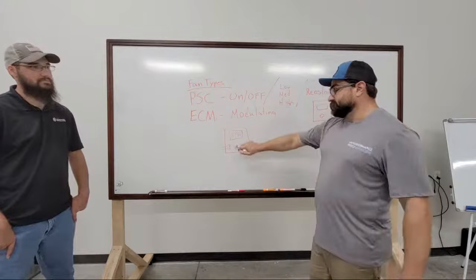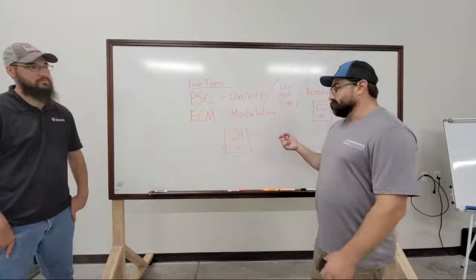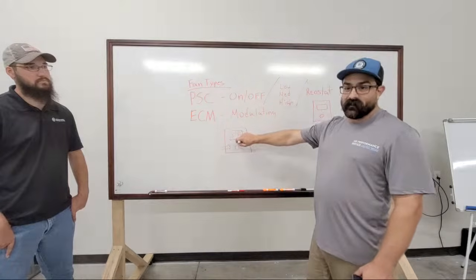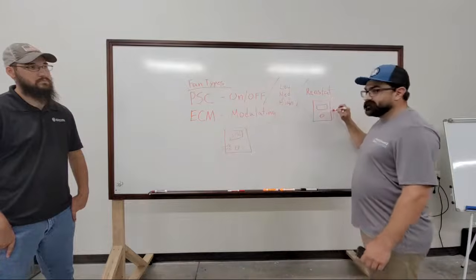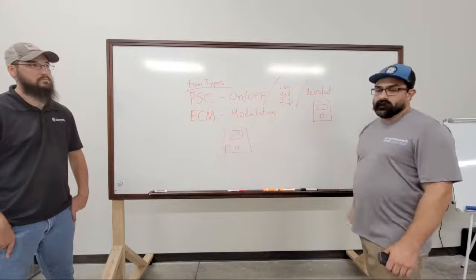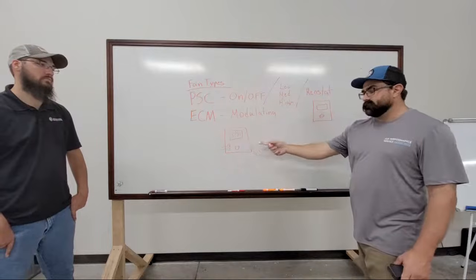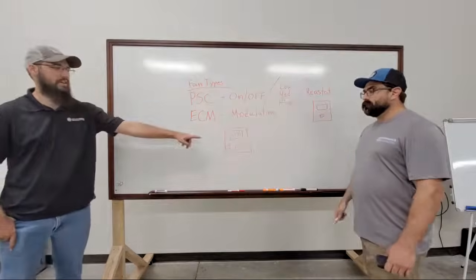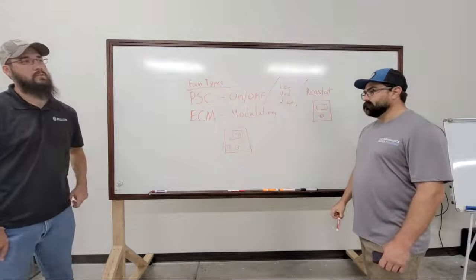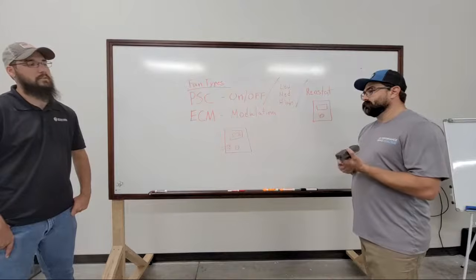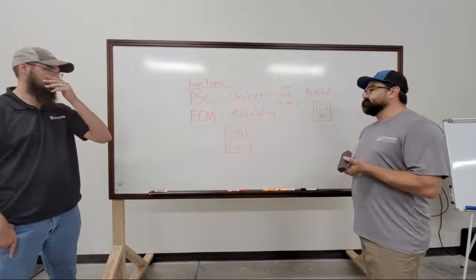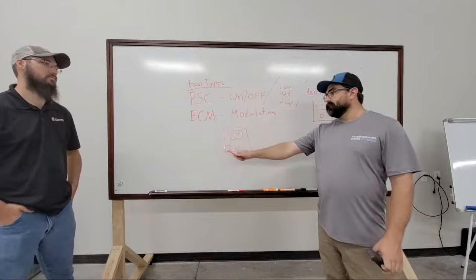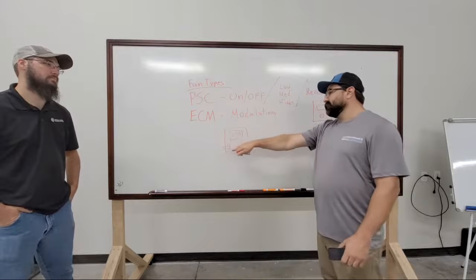But most of the time they just do it through this dial on the board. One thing about ECMs is 9 times out of 10, this board is going to be inside of the cabinet, whereas the rheostat is mounted externally on the cabinet. Some of these will be external. It just depends on the manufacturer, but these are always external. I think I've seen Titus put those external. I don't think I've seen anybody else do it. If they're external, they don't have this feature typically. We can't do anything with them.